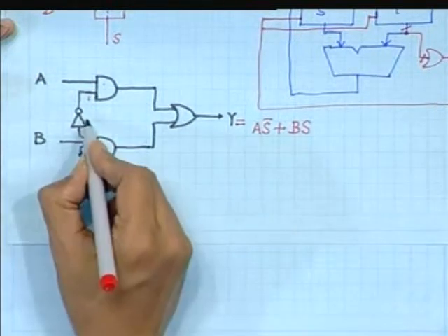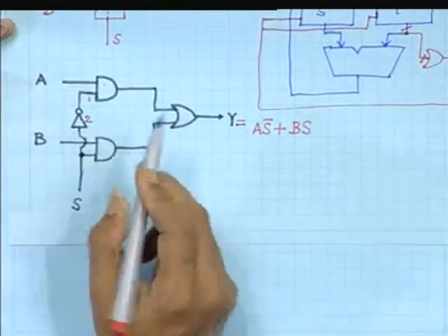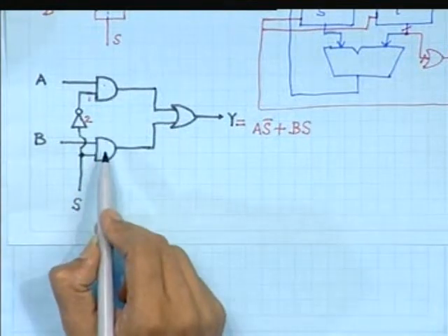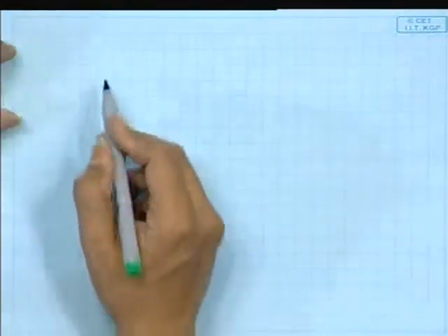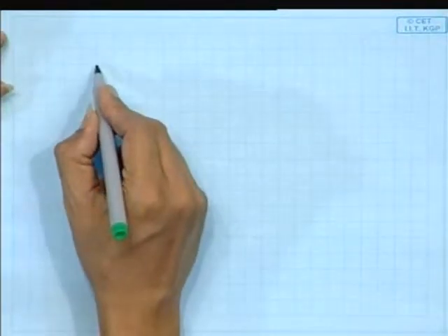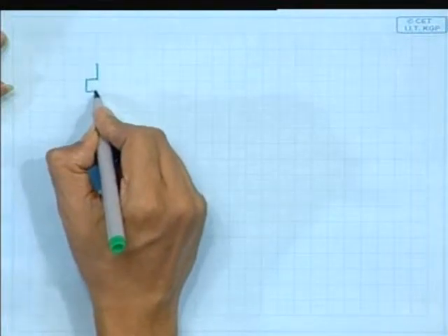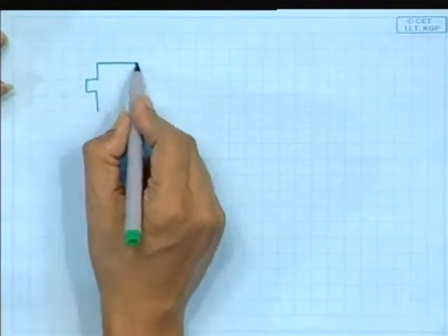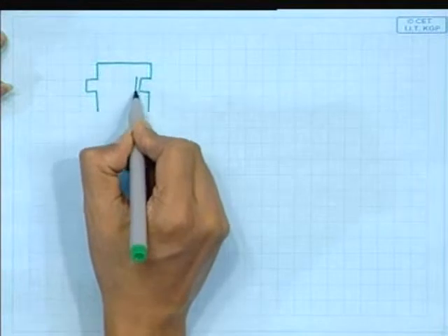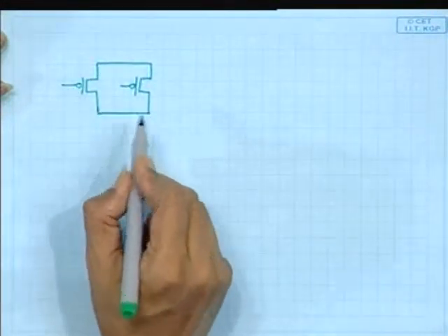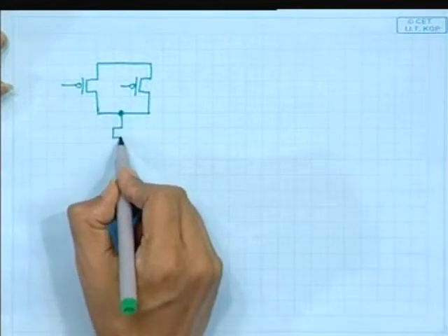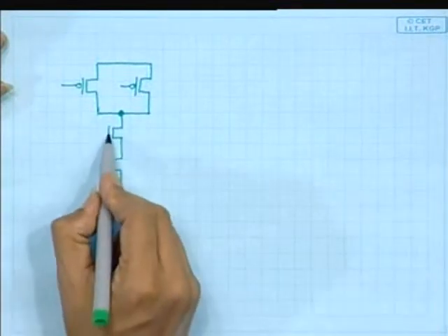We already know, 2. How many transistors for an AND gate? It will actually be 6. Inverter we have already seen. If we look at this structure, there are 2 p type transistors in parallel and 2 n transistors in series.